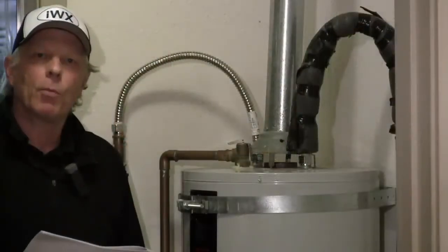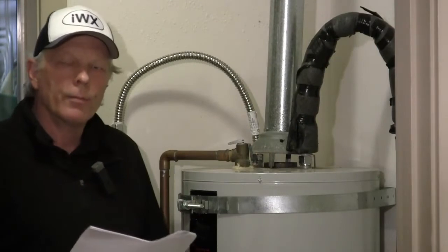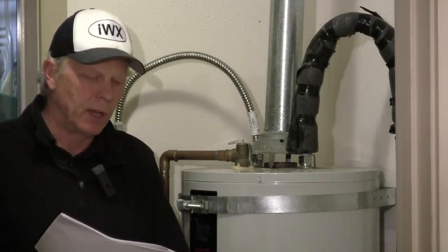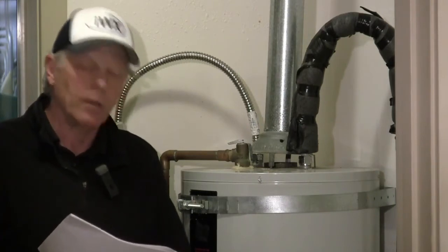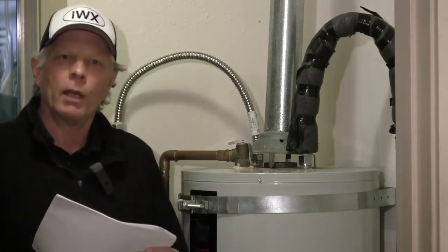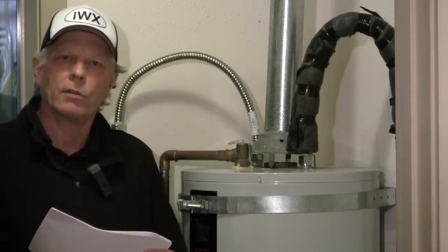Okay, we've wrapped up the combustion appliance zone section of the field guide, and we're moving on to the next section called combustion safety and efficiency testing, oven and stovetop testing. We're going to start on line 1, and this is where the candidate measures the CO in the water heater flue gases.